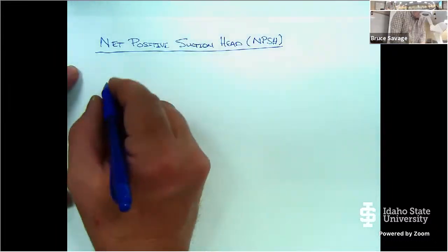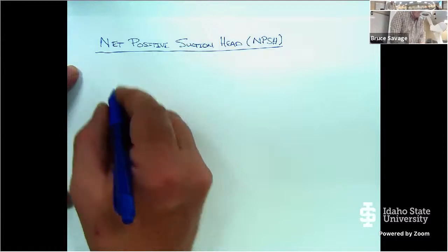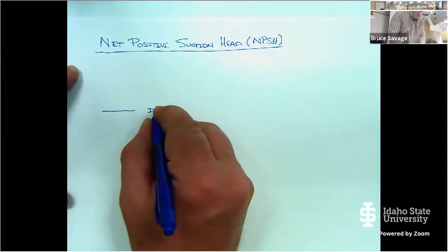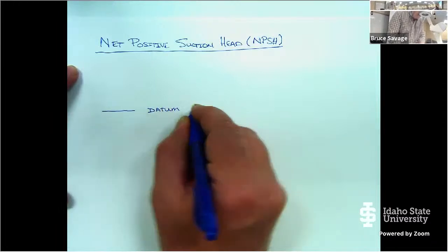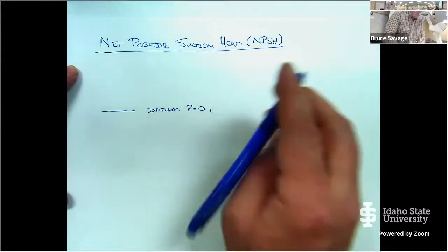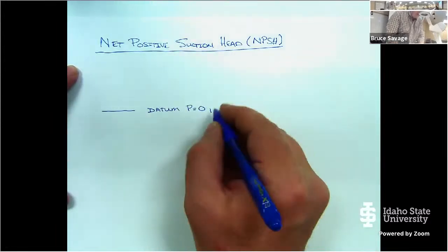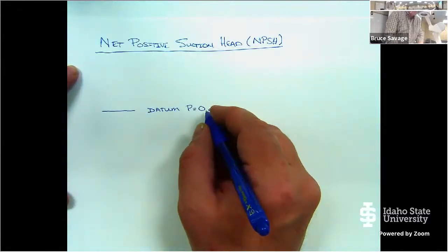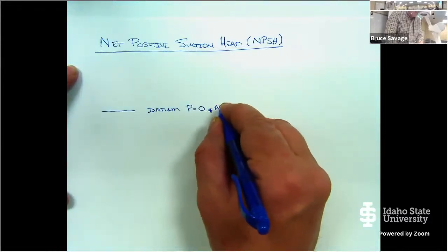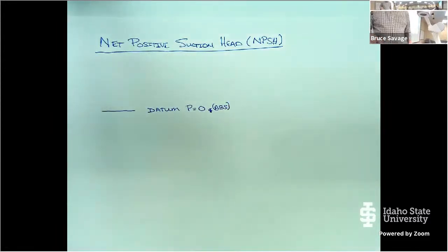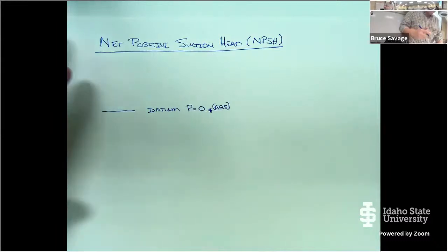Now, if you remember from the first part of the course, or going back to your basic fluids, we have some datum down here. And this datum is P equal to 0 absolute. It could be in either the metric or the English system. So at absolute 0, we have no pressure. There are no molecules there.